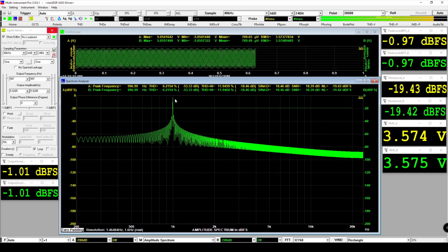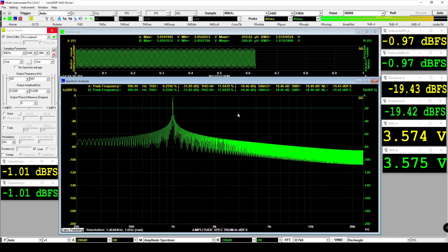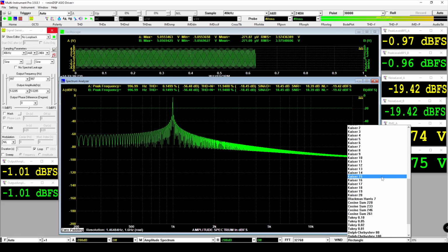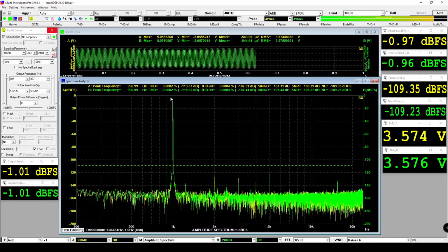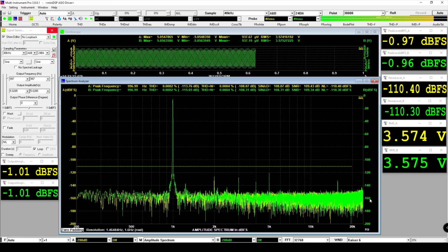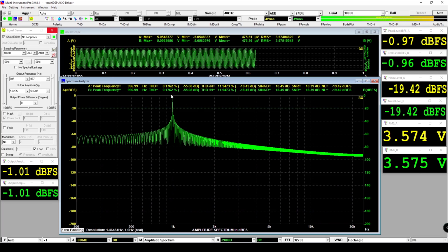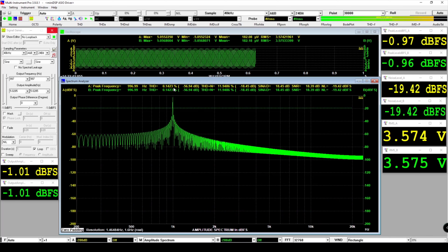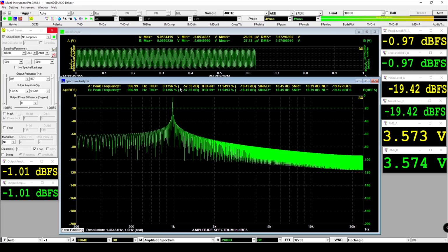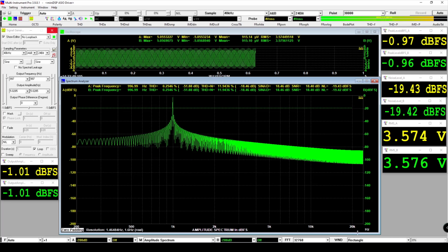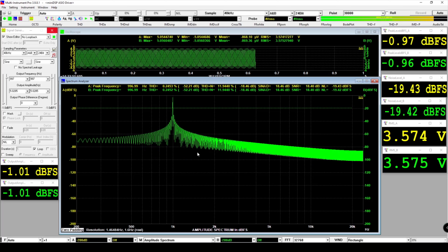That's actually one of the reasons I'm having a -1 dBFS signal, but in most of the windows, like what I had here before, the signal is lower than -1, because that's also an effect of the window function. If you put the rectangle window, then I think it's about -1. Again, with this rectangle window, if you look at the THD and all these numbers, they're very awful because the signal looks awful here.